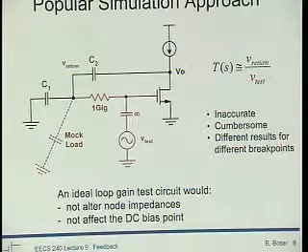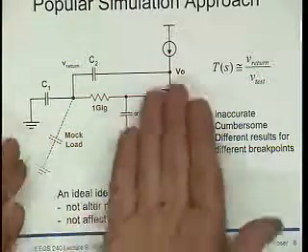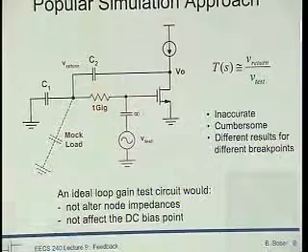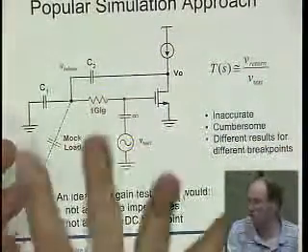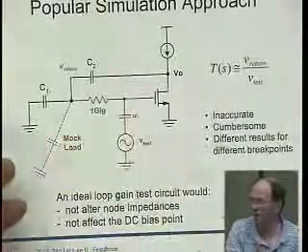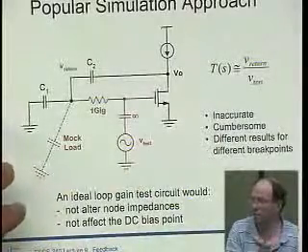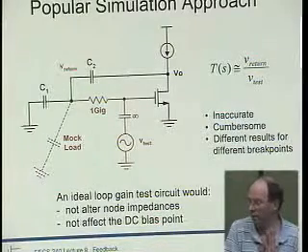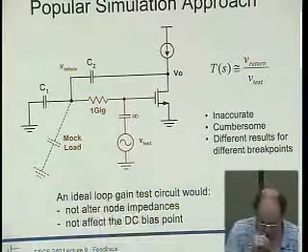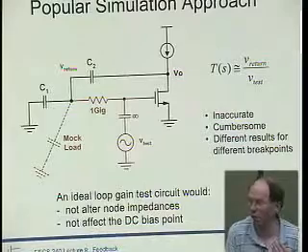It seems that sometimes the operating points are so off that what's supposed to oscillate doesn't oscillate, etc. Well, when you do this analysis, you have to make absolutely sure that the DC operating point of your analysis and the operating point of the actual circuit, how you use it, are exactly the same.